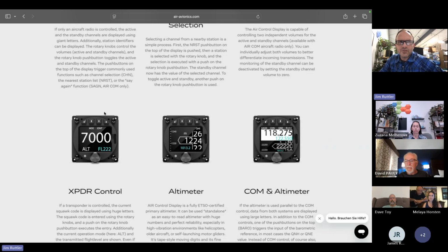If I can get that from my current Dynon Advanced setup over to it, I would like that, because one of the limitations I always find is that when I zoom in on the map view for approaching an airport, I might want to zoom in or out independently of getting a traffic view. Right now the traffic is tied to my zoom level for my terrain, and I don't like that. I'd like to have something fixed, a 5 mile or 10 mile radius that never changed.